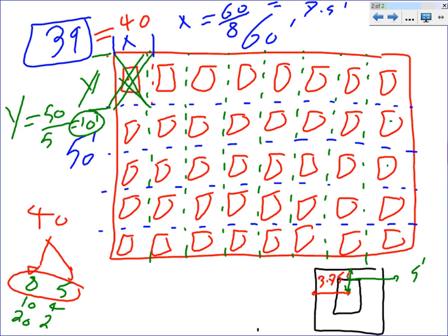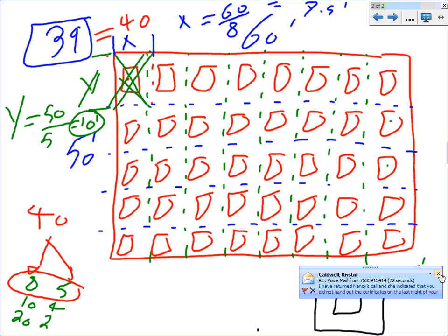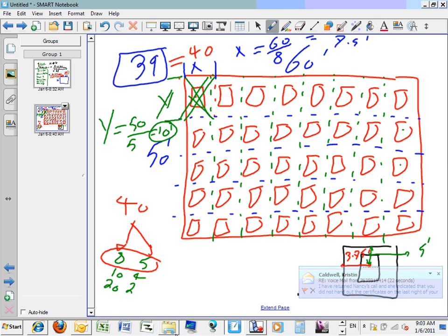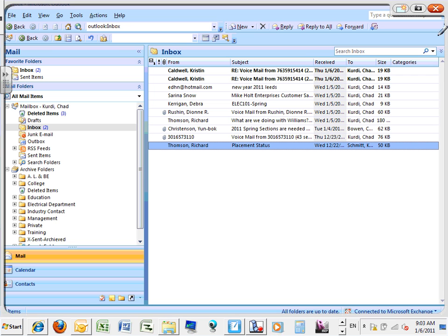Always, when you lay out your fixtures, please always work square or rectangle, and then modify the design based on 2 criteria. Number 1, the grid, if you have a grid, and number 2, if the shape is different. What if that was a circle? A circular shape, an arc shape. What if the arc was coming this way? Then you might have to get rid of some fixtures. But at least, guys, what I like about this is it gets you some type of a layout to start with.